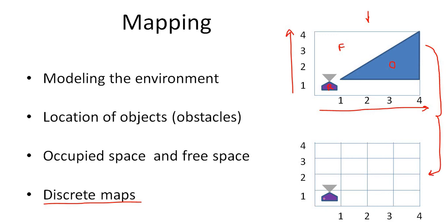And initially, our robot doesn't know where the obstacles are located. What it does is divide this whole room into boxes or cells of 1 meter length and 1 meter width. It must not always be 1 meter. It can be of any size, and any number of cells can be there. The smaller the cells, the better the resolution of the map. So more small obstacles can be detected with small cells.